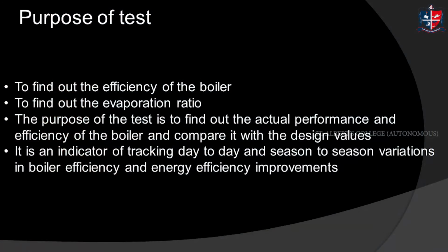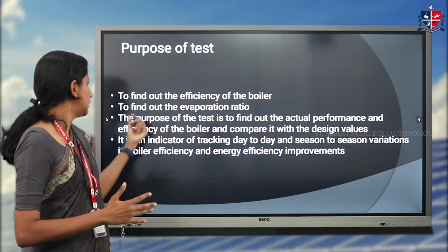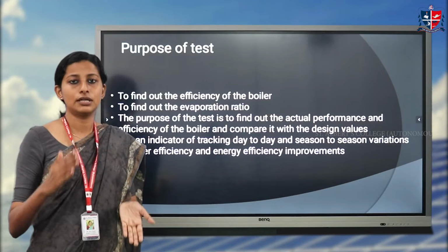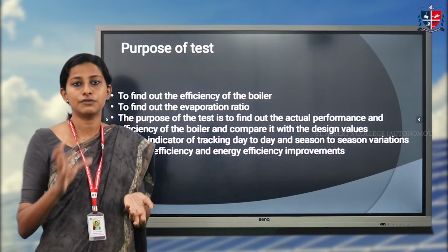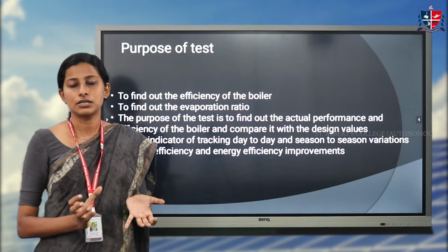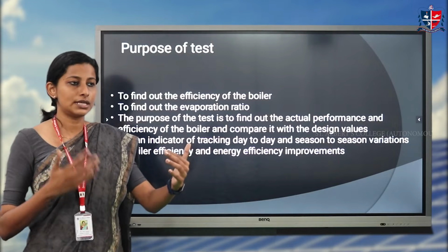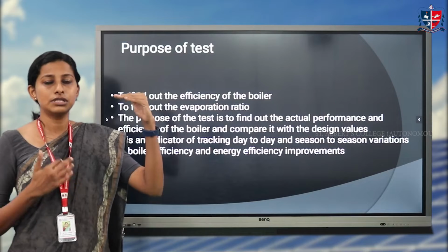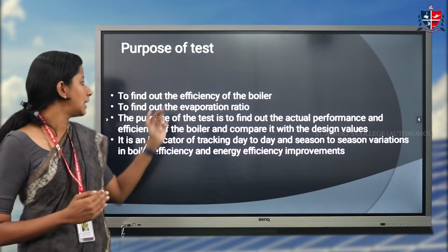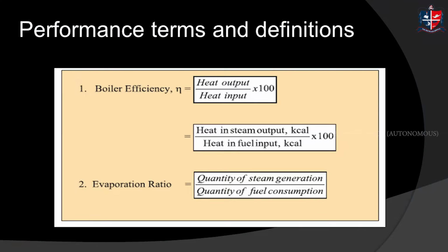So the purpose of the test, just summarized: one is to find out whether the efficiency is good and the evaporation ratio is good. Next is to find out if it is up to the standard, if it has met its actual rating. We know every device when we purchase it has a rated efficiency or a rated set of standards. What we need to know is, as time goes by, whether its quality is degrading or whether it is still performing up to its rated efficiency. That needs to be known. So that is the purpose of the test. Let's see how we find out.